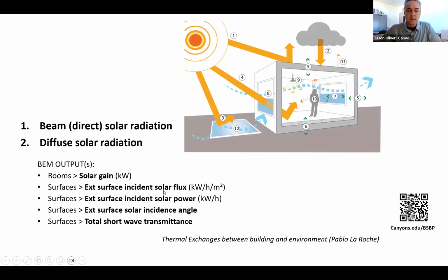And so we can, in the case of the level of a room or individual surfaces, start to use this data to inform the geometry of a building, that exterior envelope, and to inform us of the need for shading, or to inform our decision making about the percentage of fenestration or windows. What we look at is, for instance, the window to wall ratio. How many windows do we want to have on a particular exposure? And part of that decision-making process involves, how much solar heat gain do we want to admit into the building?